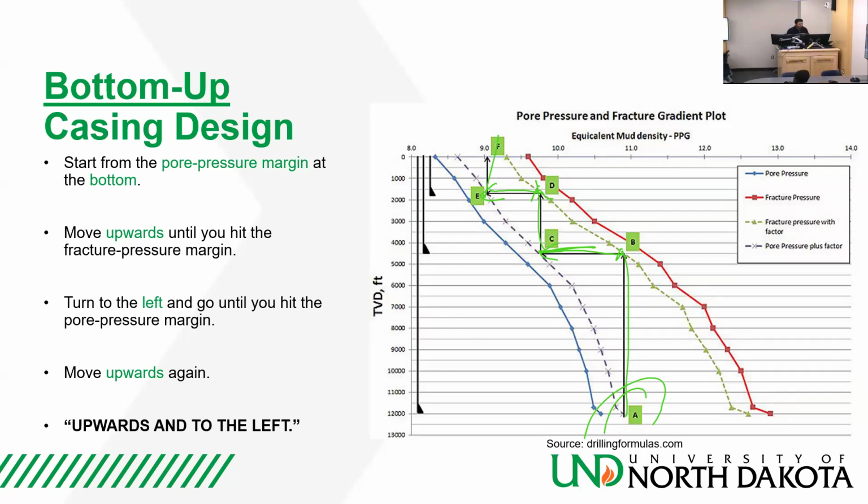Okay, how many casing strings do I need now? Three. That's correct. I need one up to 1800, I need another one to 45, and I need another one to 12,000. So how much total casing string do I need? Add 12 and 45 and 18 up, you get the value. Any questions on that method?